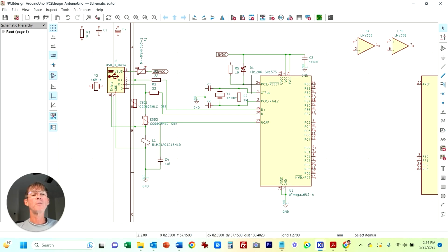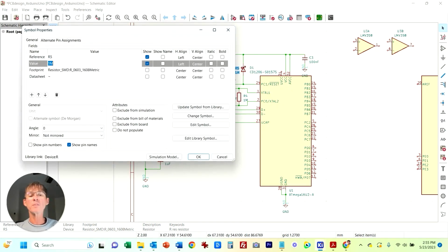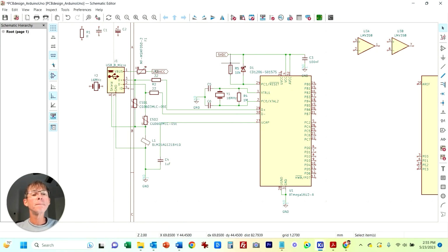So basically, if you're not pulling it down low, the pull-up resistor holds it up high to the positive supply. But if you force it low, then it will go low because this resistor can only pull up a certain amount, because it's going to be 10K, so it's a pretty good size resistance. Okay.